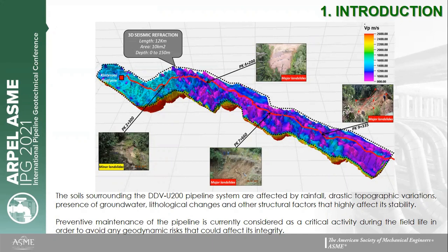The study has included a processing of field seismic gathers data in conjunction with LIDAR DTM topographic information, with which a 3D model of P-wave velocities was constructed, a calibration of the P-wave velocity model with field data, and an interpretation of the final P-wave velocity model.